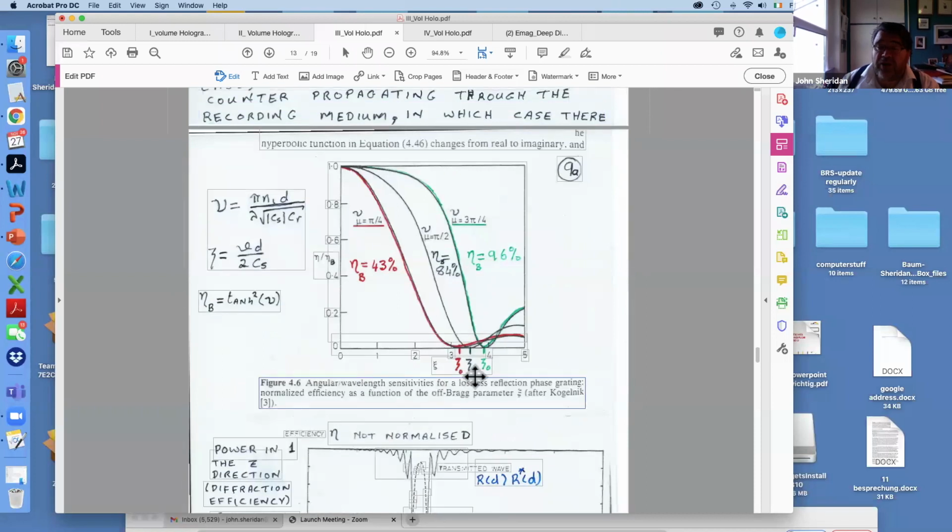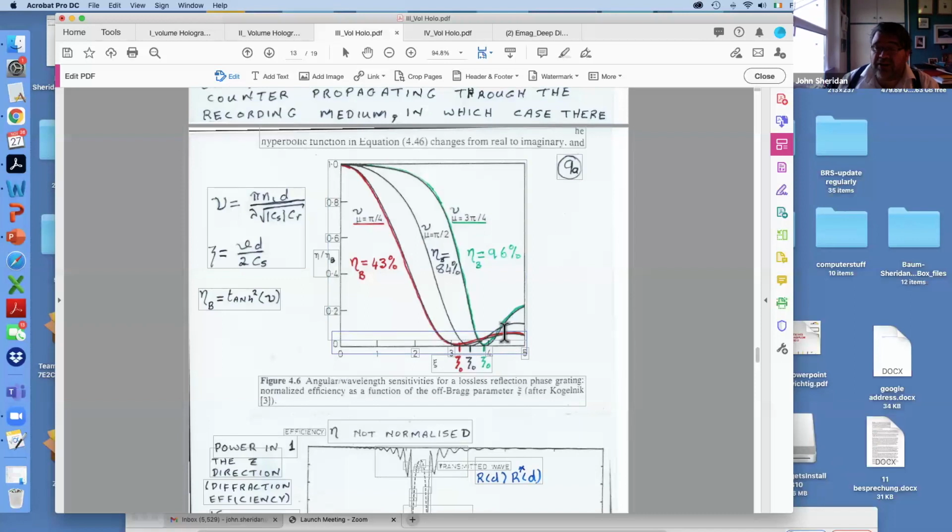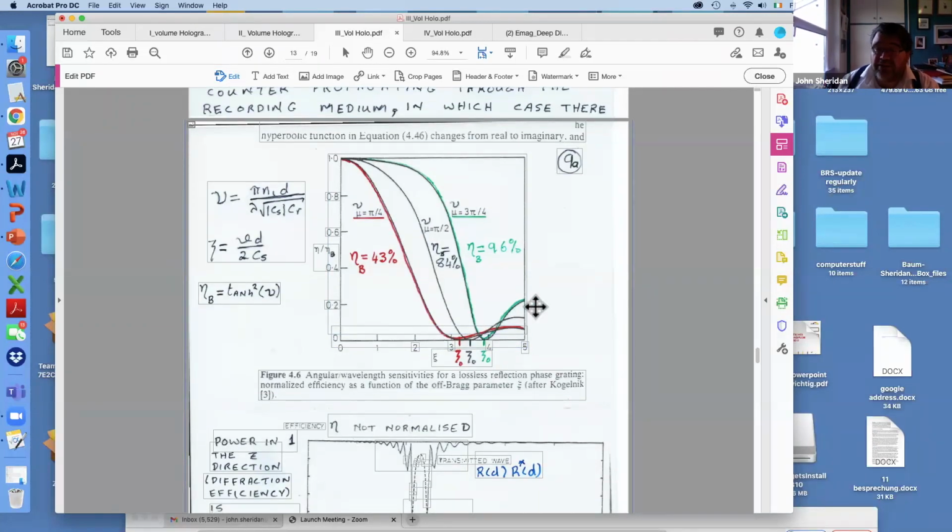Okay. And again, what do we see? Well, as we increase the diffraction efficiency, as we increase nu, the first zero point moves outwards. And furthermore, as we increase the on-Bragg diffraction efficiency, the relative size of the first lobe increases. We have this nice characteristic, though, that as we increase the grating strength, we're getting something which looks more and more like a very nice rectangular filter. So we get this rapid roll-off of the filtering effect. Okay, so we've got a filter, it's very flat over this region if we're varying wavelength, for example, and then we get this very rapid roll-off over here.